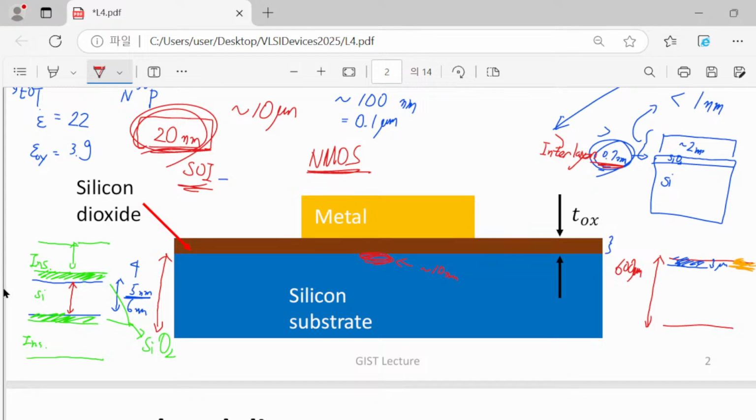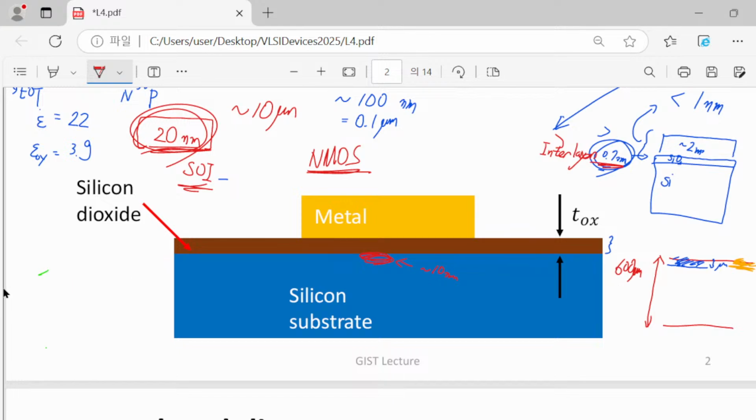This is a long story, but let me just make it quick. If you want to introduce a certain doping, usually what we do is so-called ion implantation. However, in such an advanced technology, with a silicon layer just 5 or 6 nanometer thick, this thickness is not defined by other means, but by epitaxial growth.